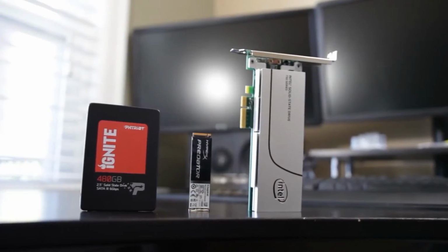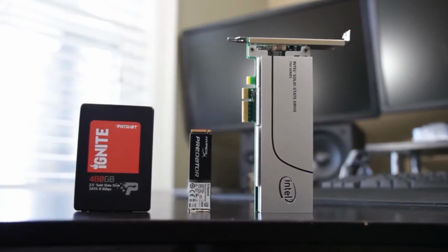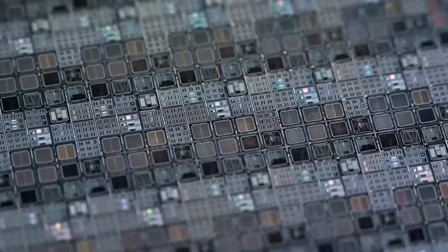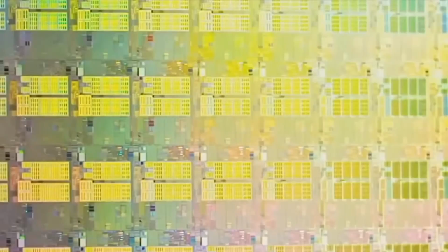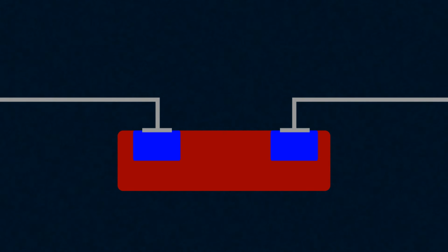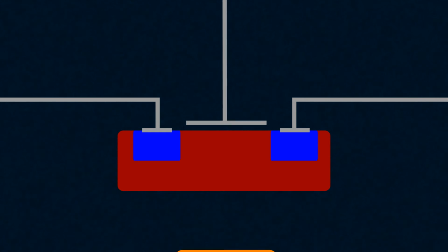It also relies on field effect transistors, but not ordinary ones, but slightly modified ones, so-called floating gate transistors. So, what is a regular field effect transistor? Essentially, it's a piece of P-type semiconductor with 2 pieces of N-type semiconductor embedded in it. Contacts are connected to both N-type semiconductors, leading to our circuit. In addition, another contact, called the gate, is brought on top of the region between the N-type semiconductors, which is necessary to control the transistor.